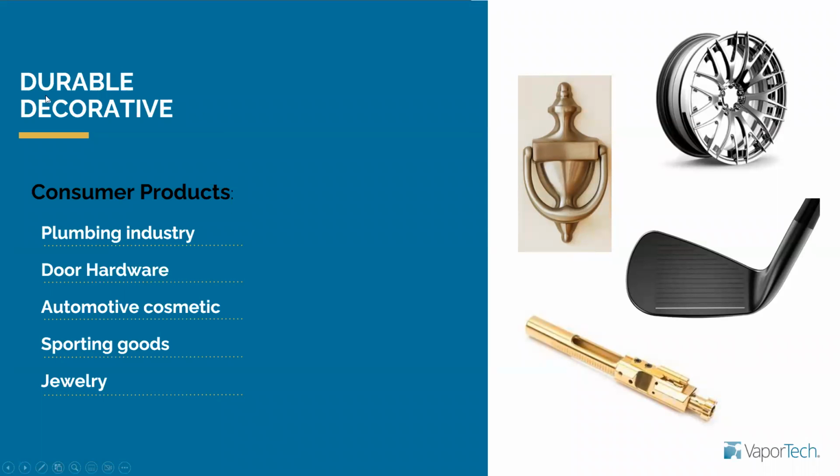In terms of decorative, whenever we talk about a PVD coating or a PECVD coating that has a decorative application, you have to think that it is durable as well. This is not paint, right? This is a process that applies a hard coating to the surface of your part that is very durable, very high hardness, very good adhesion, and it's going to last a lot longer than if you just paint that part.